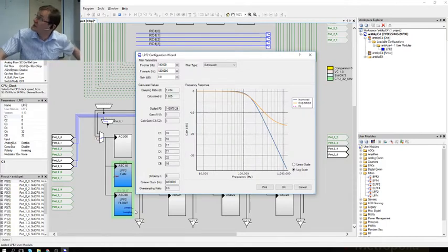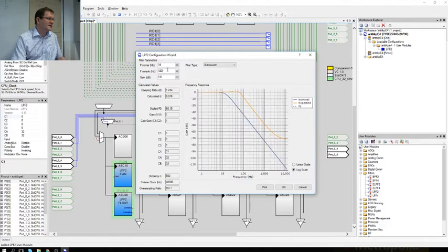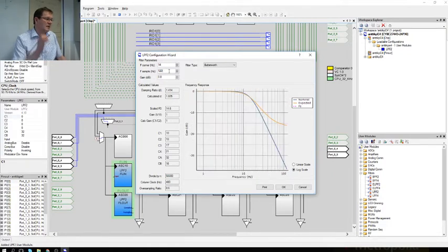There. Doesn't it look much better? And we basically are shooting for a corner frequency of about 10 Hertz. How to do it? Basically, you go and start reducing these. Let's see. Does it go to that one? Yeah, it actually does. That's nice. So now I got 14 Hertz as the corner frequency.